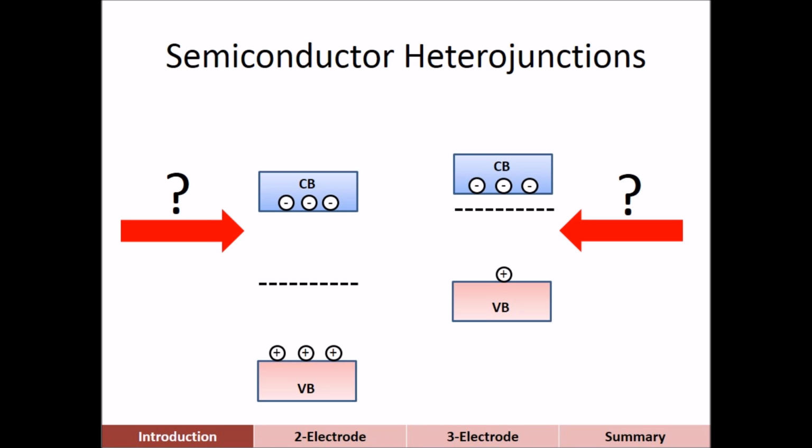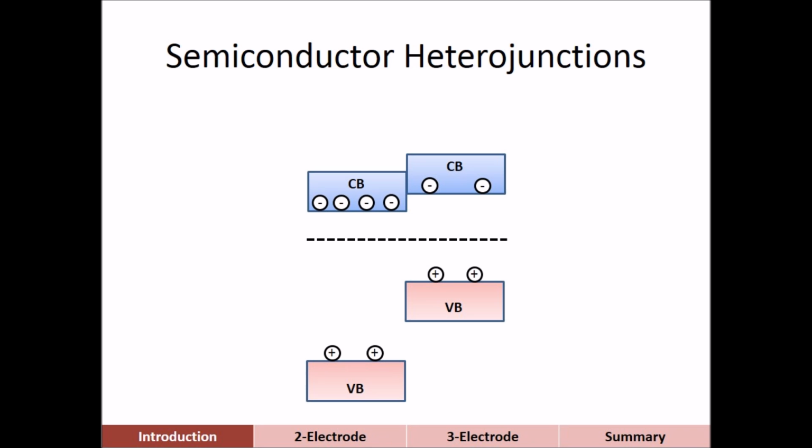So in our quantum dot solar cells, we're often constructing them with semiconductor heterojunctions, so 2 semiconductors in contact, such as a TiO2 electrode coated with QDs. And when we bring 2 semiconductors with different Fermi levels into contact with one another, we see both hole transfer and electron transfer such that the Fermi levels reach an equilibrium. So there is one common Fermi level across the entire composite.